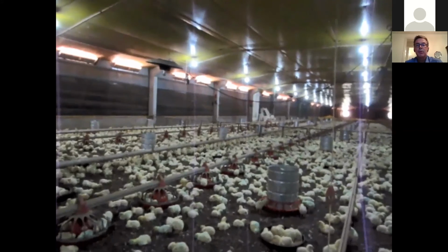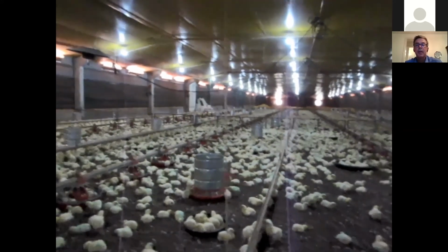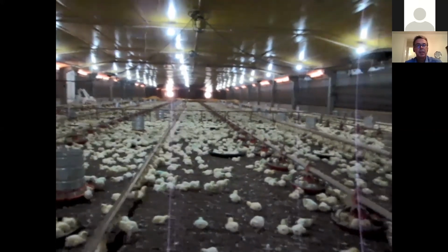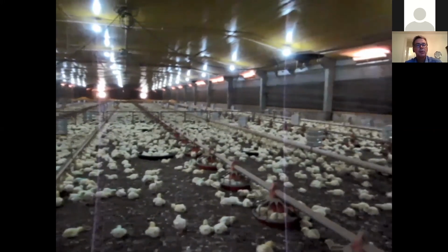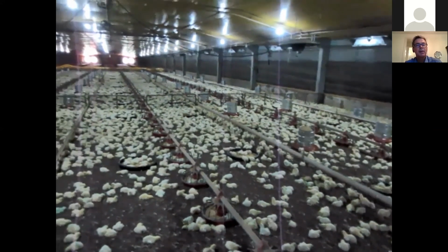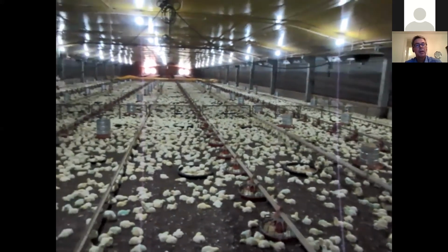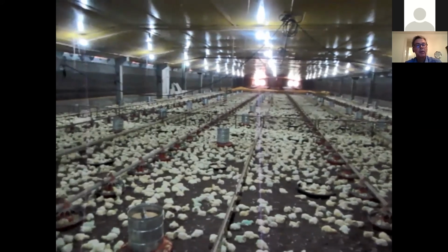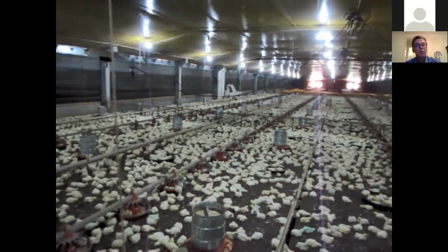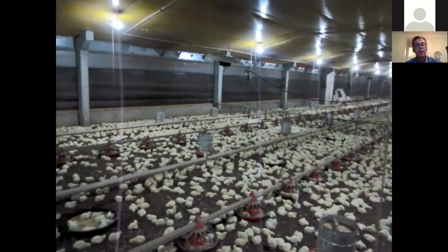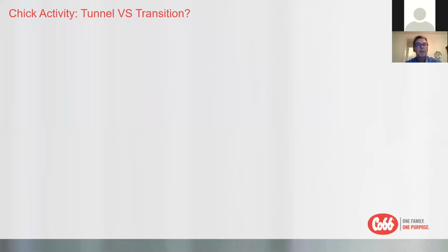Everybody in the broiler industry for sure knows that the minute you start running tunnel ventilation, you change activity. In this house, we had 2 tunnel fans on in full transition mode, but instantly 2 more tunnel fans come on, and what we see, instantaneously, is the birds go down. The minute you put that extra movement across the chicks, they respond very quickly. They stop drinking, they stop eating. When you don't have consumption, you don't have growth, you have poor uniformity.